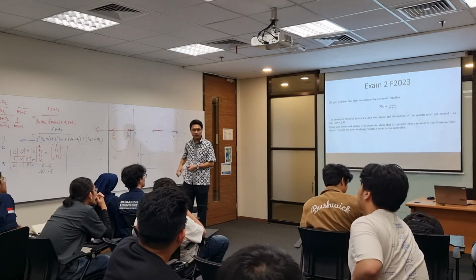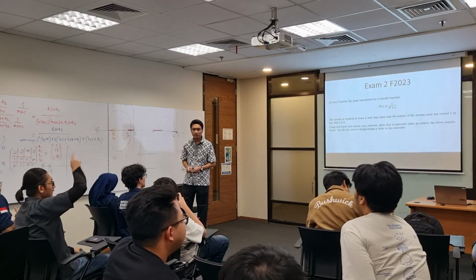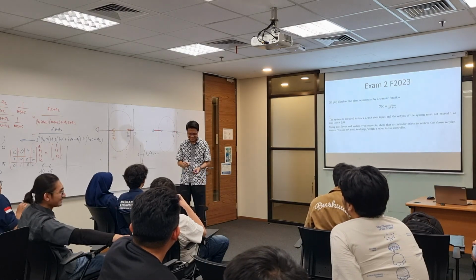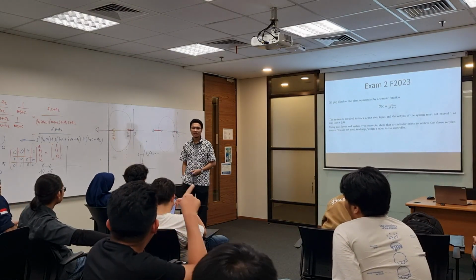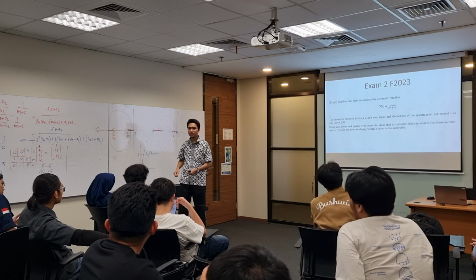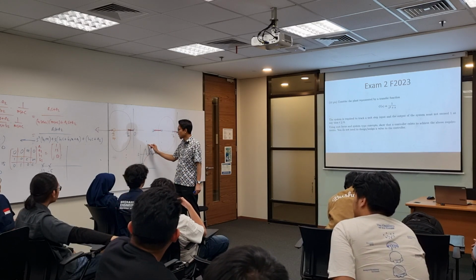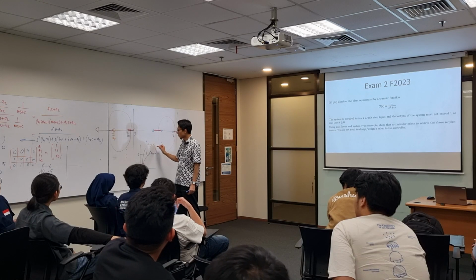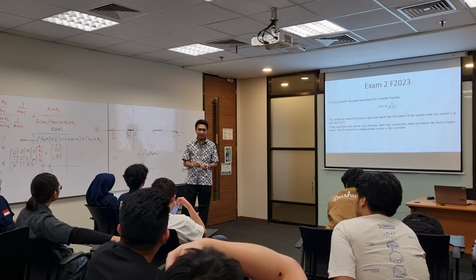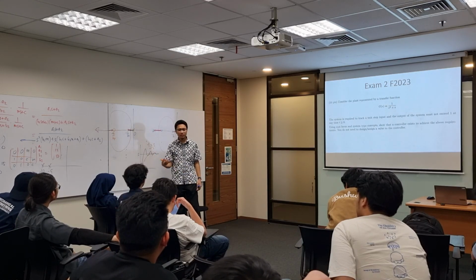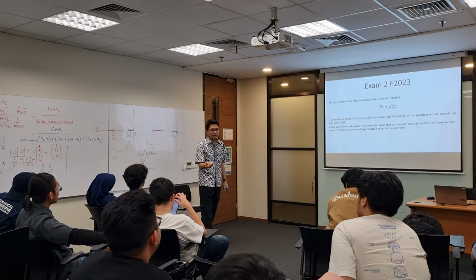The input is a unit step. Underdamped will be like this. Critically damped, no overshoot. So at least your zeta is 1. You know from that your zeta is at least 1. It can be 2, 3, 4, or 1.01.